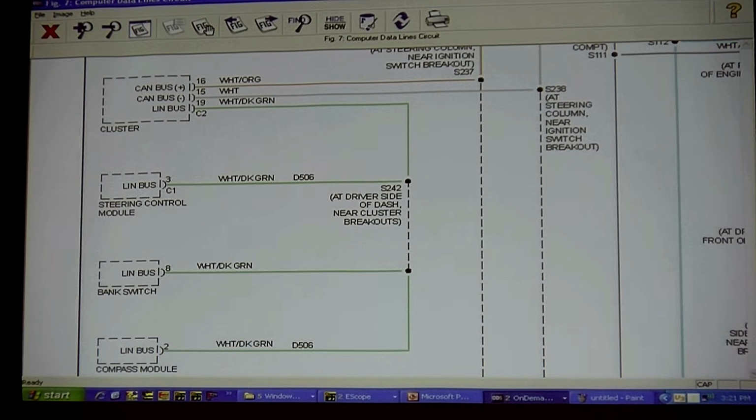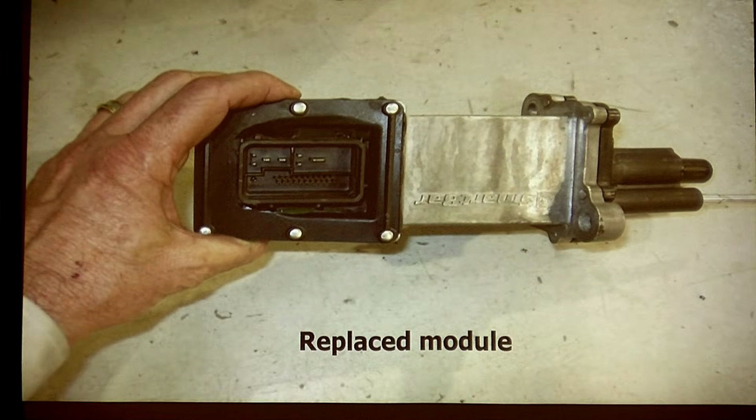Here's the wiring diagram. We want to come down. We can see here that we've got my LIN system. Who controls the LIN bus? The instrument cluster. And he comes down. Can this be right? No, because it says that guy's on CAN-C. So the wiring diagram does not match the car. That's what I'm trying to show you. Now what am I going to do? I'm going to go look at the module he took off the car, because that's easy.